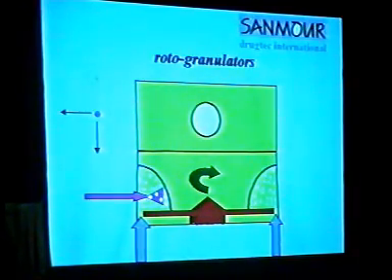Due to these three forces, the pellets are often found to move in a rope-like fashion. So therefore, the pellet turnover rate against the spray nozzle and the spraying junctions is quite fast. Thereby, the spray rates are very, very high, and the drying rate is very high. It has a spin drying effect.